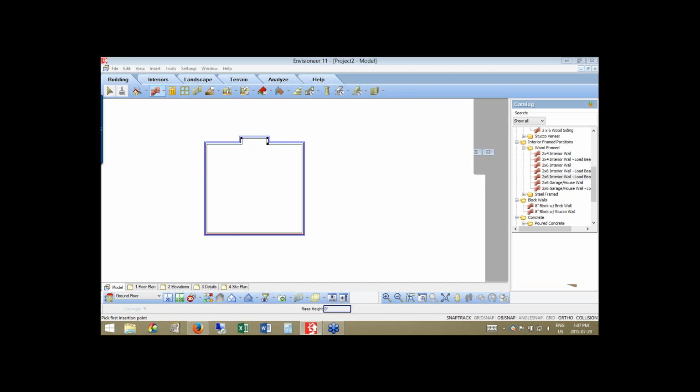If you don't see it, that means they're not seeing each other in a connection, and you're not going to have a nice, clean intersection at that corner. So always take a moment, see the circle with an X, left click then, and then pull. And as I pull down to the wall below, that perpendicular wall, I'm going to do the exact same thing. I'm going to wait, see the circle with an X. When I see it, I left click.